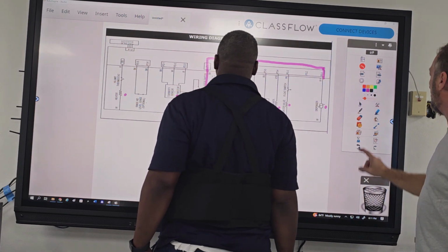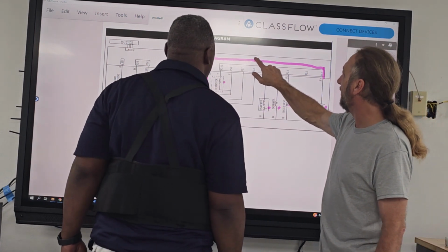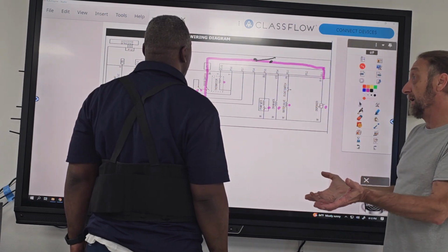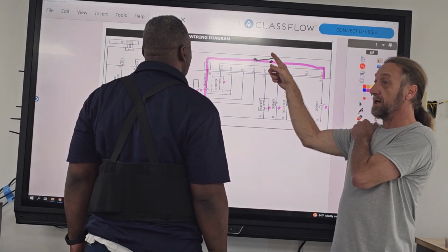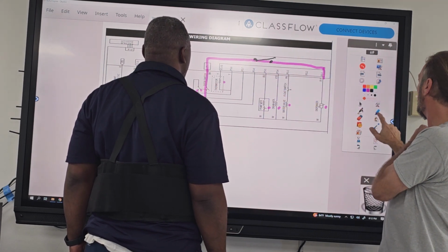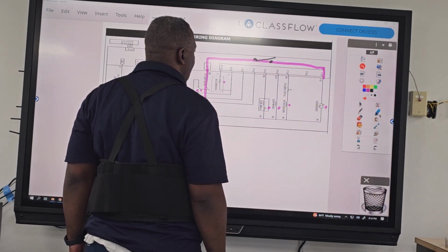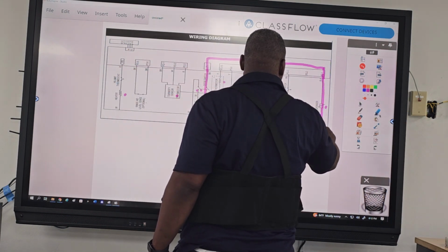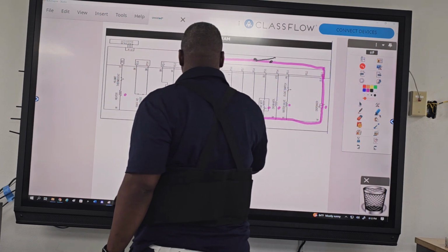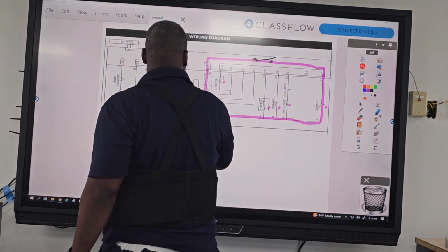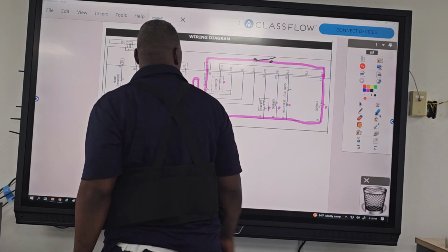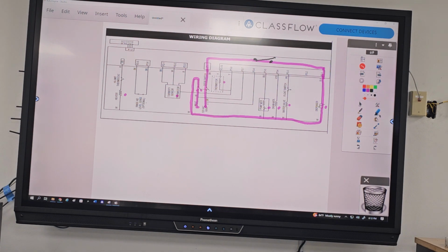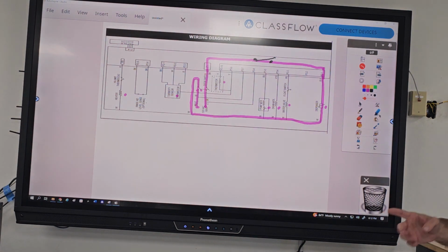Let's stop just for one second. So somewhere here on the board is a switch. That would be a relay. So when the board wanted a dispenser, it would close that switch and send power there, right? Okay, so where's the rest of that circuit? Go through the dispenser, where does it go from there? Okay, very good. So that's how power goes through that diagram, just to energize the dispenser.